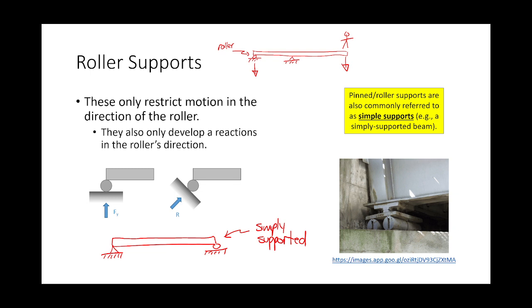So one of the things that we do in bridge engineering is we use what are called fixed and expansion bearings, right? So on one end, the device that connects the bridge to the abutment will be fixed, and on one end it will allow expansion. Typically, the way that we do that is we'll use plates with bolt holes that are either circular or on the other end, bolt holes that are slotted that allow a little bit of translation. Now, why would you want that? Why would you want your bridge to move a little bit left and right? The answer is temperature, okay?